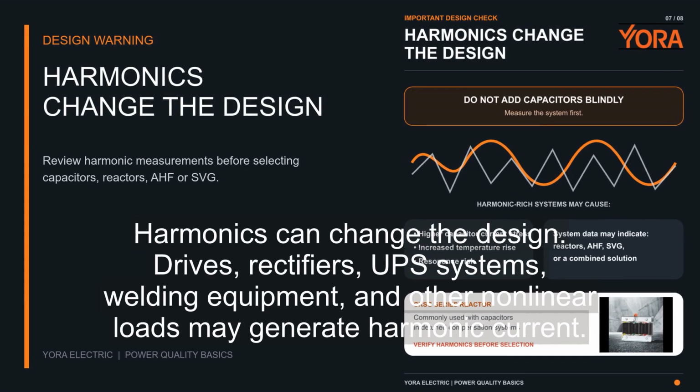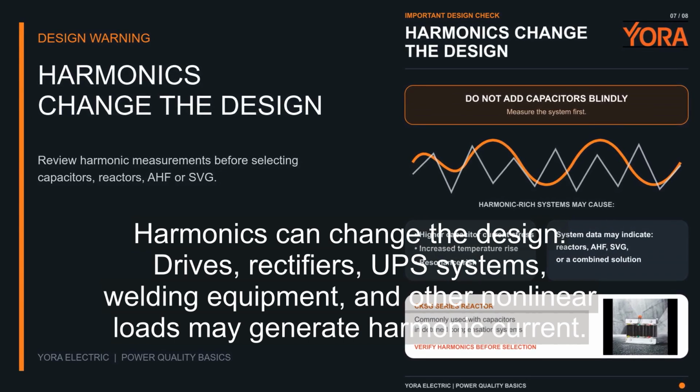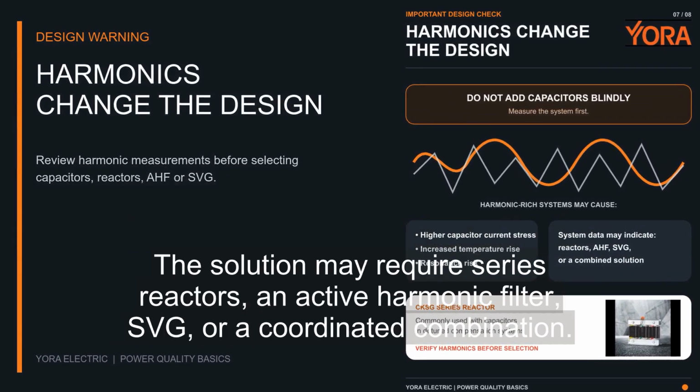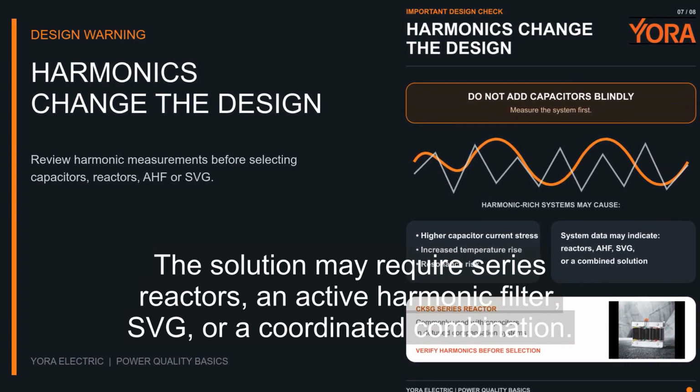Harmonics can change the design. Drives, rectifiers, UPS systems, welding equipment, and other nonlinear loads may increase capacitor stress or resonance risk. The solution may require series reactors, an active harmonic filter (SVG), or a coordinated combination.